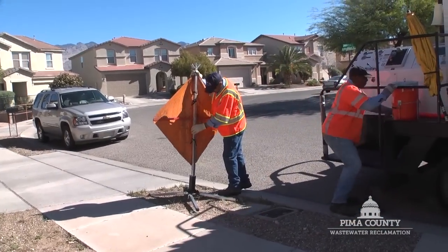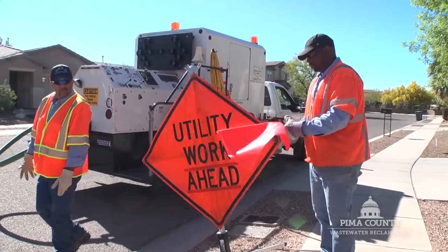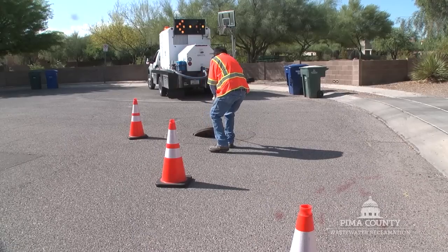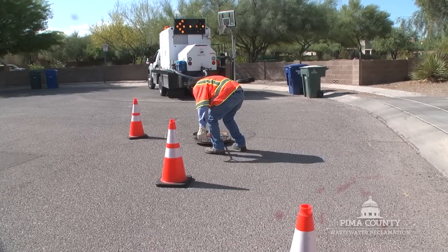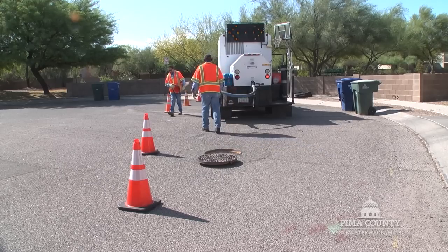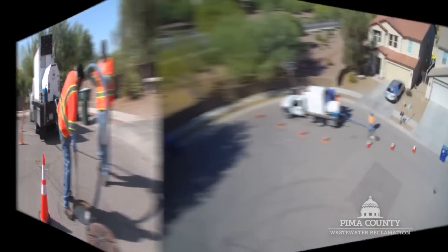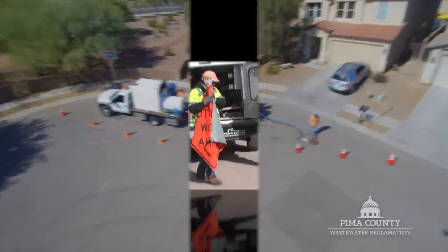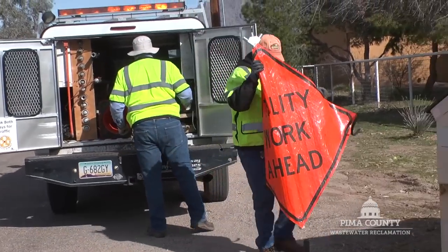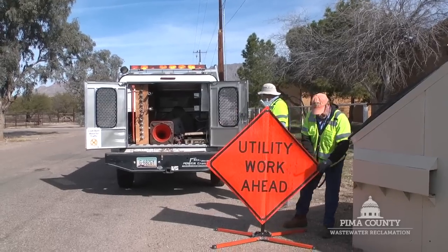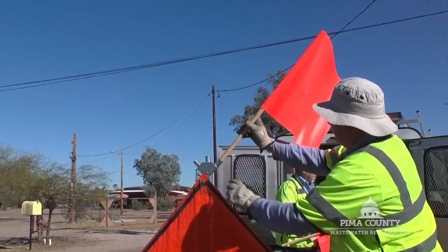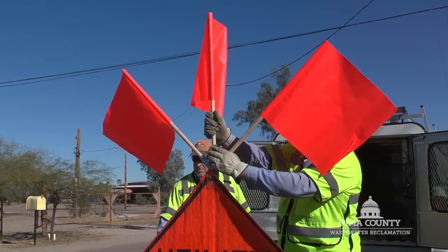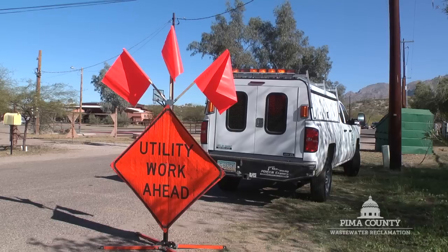For those instances when low hazard setup is needed and the traffic control supervisor does not need to be involved, the work crew will set up the required cones and signs around the work area only. The 5 components are not always needed here. The flow monitoring group will perform their own temporary traffic control setups if those setups are considered low to medium hazards and if they have the appropriate equipment for the setup.